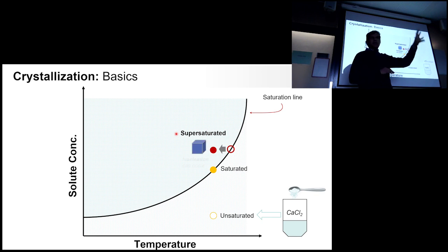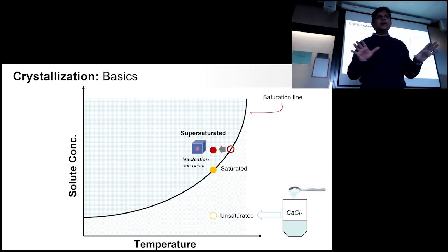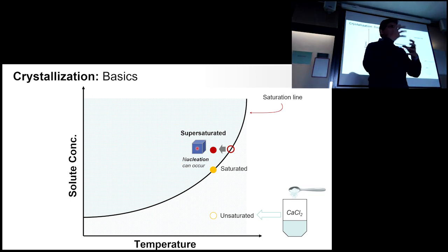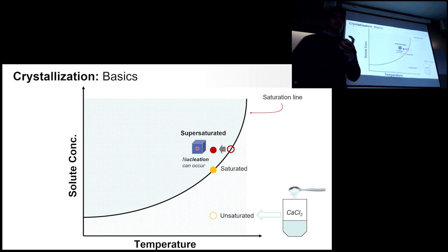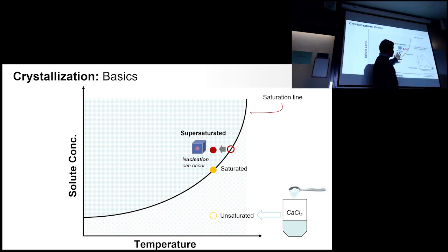But sometimes this nucleation has to be induced. Have you seen any YouTube videos of liquid ice by any chance? If you take DI water without any ions, and you freeze it, you take it out very gently and place it on the table, it will not freeze. But if you put a tiny bit of ice crystal into it, or you shake it, it will suddenly crystallize. So it requires some trigger for this crystallization to happen.